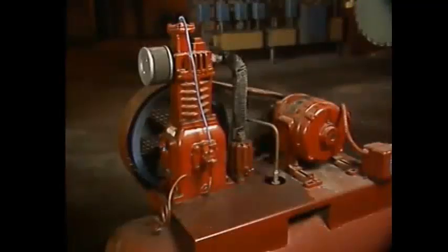Pressure regulating methods range from a simple on-off system to more sophisticated methods, such as the use of inlet valve unloaders. When pressure is regulated by a simple on-off system, a sensor in the receiver controls the compressor's drive mechanism. When the pressure in the receiver increases to a preset value, a signal is sent to stop the compressor. When the pressure in the receiver drops to another preset value, a signal is sent to restart the compressor.